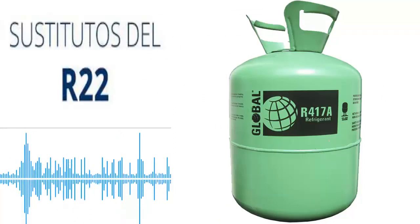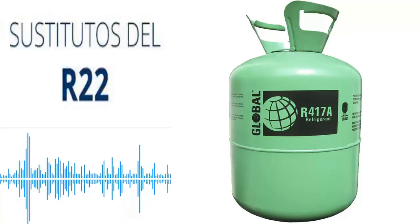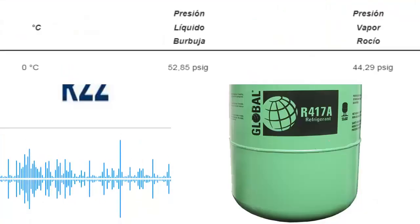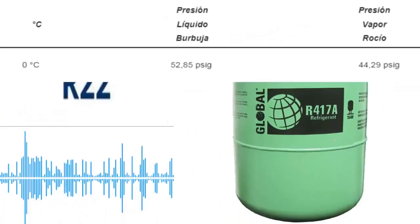However, the refrigerant R-417A can be used in refrigeration applications at medium temperature. For an evaporator temperature of 0 degrees Celsius, a pressure of 3.05 bar is needed in the low side of the evaporator, equivalent to 44.29 psi.